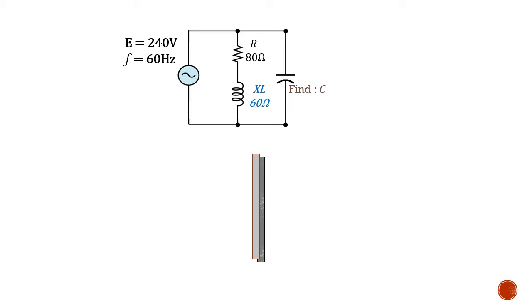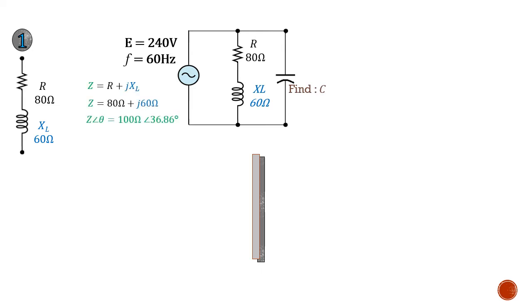First, we'll do a quick reflection back on doing a power factor correction problem. In this particular problem, we had 80 ohms in series with 60 ohms inductive. And the first part of it is to find all the values for the RL circuit. So we isolate that out. And then since these two are in series, we would follow the procedure of finding your total impedance. Once you have your total impedance, you can get your current for that branch as well as the angle of the current.